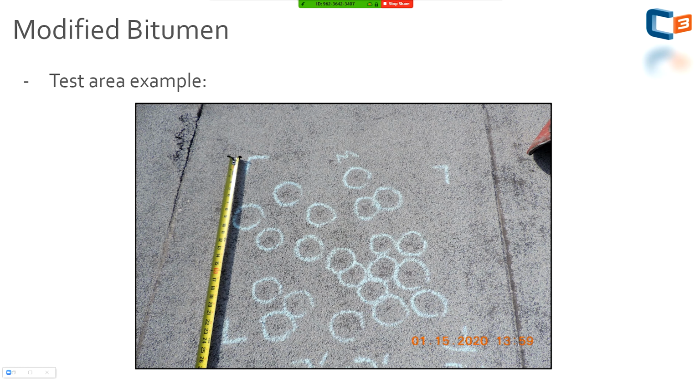And you see kind of dirt gathered in the area. And these areas were dimpled just slightly. And a lot of times what you'll find is dirt gathering in these low areas can indicate you have an impact that depressed that area downward. In this case, too, we had a very subtle star fracture, but what we did, we identified areas where there was dirt kind of gathering in these areas. It was very bright, so we had to look very closely. There was actually a little bit of a concentric fracture on the coating. This also had granules, so at some point maybe this got to be a little worn out, someone coated it.